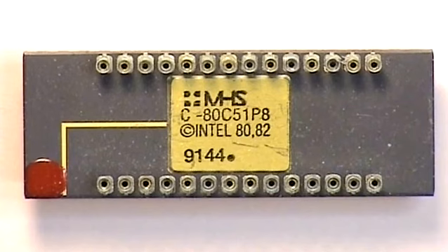To test the program, I use a special microcontroller of the MCS51 series, namely a piggyback microcontroller by the manufacturer Harris Semiconductor. This microcontroller leads its ROM area in the form of a 28-pin dual inline socket to the outside.